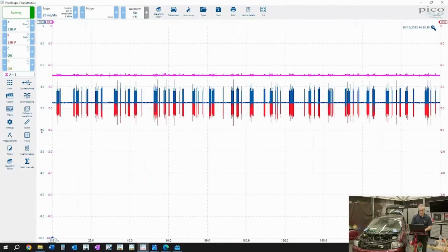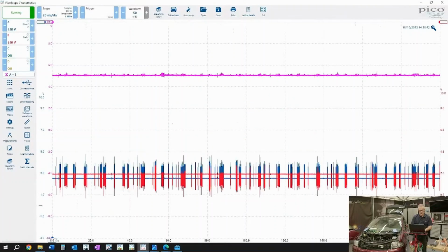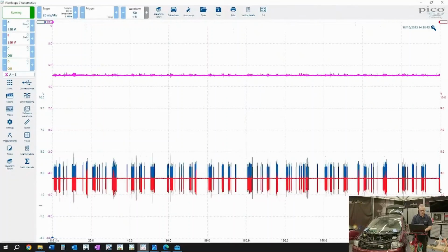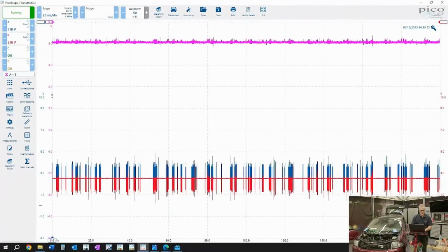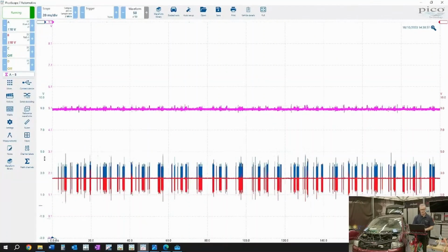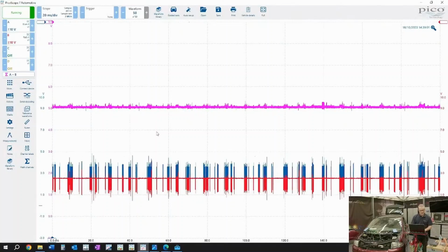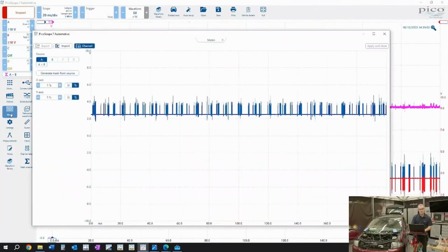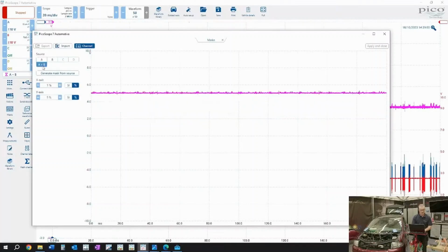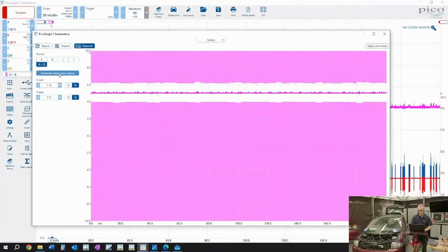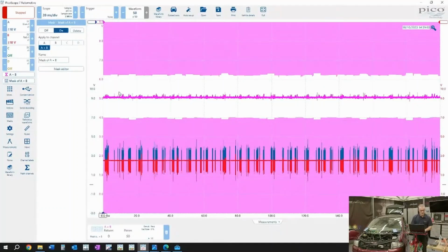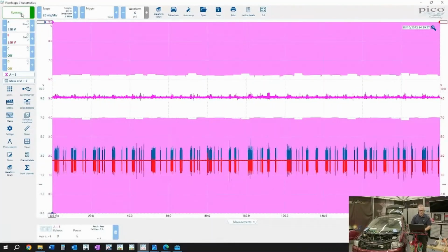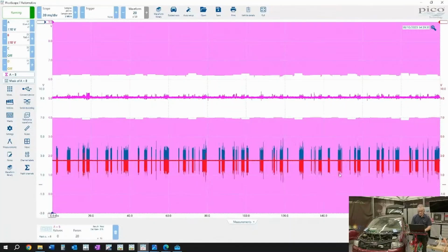What I'll do, I'll just click on our software. We can drag these waveforms just out of view, and I will then change the scaling for the math channel. So we'll put the math channel at ×2, and the reason being I can bring that down to around 5 volts in the scope view. Now we click on a feature called mask, and we'll choose which channel we want to mask. We're going to go for A plus B, and we'll go for generate mask from source. Apply the mask, and you'll see there that we have a mask drawn around our 5 volt signal, our math channel. And notice in the bottom corner, I'll just make this large so it's easier on the eye.